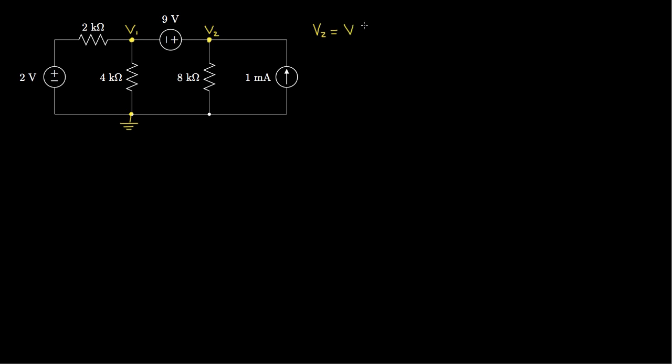again, V2, the voltage at this node, is the voltage at this node plus 9, because there's a 9-volt voltage source between them. So now knowing one of these node voltages tells us the other. If we know the voltage here, V1, then V2 would be V1 plus 9. So in effect, there's only one independent node voltage, and the two nodes could be combined, and commonly are, into something that's called a supernode.